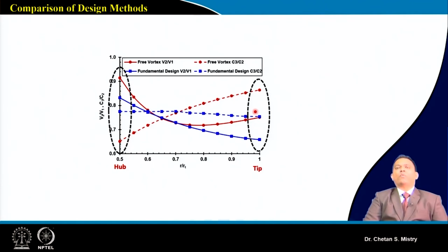In order to avoid such a situation, and to have great control over our operation, the fundamental approach gives a more systematic way of designing. We have more control over what we expect throughout our span. One more thing is that the more stations we select, the smoother our curvature will be.